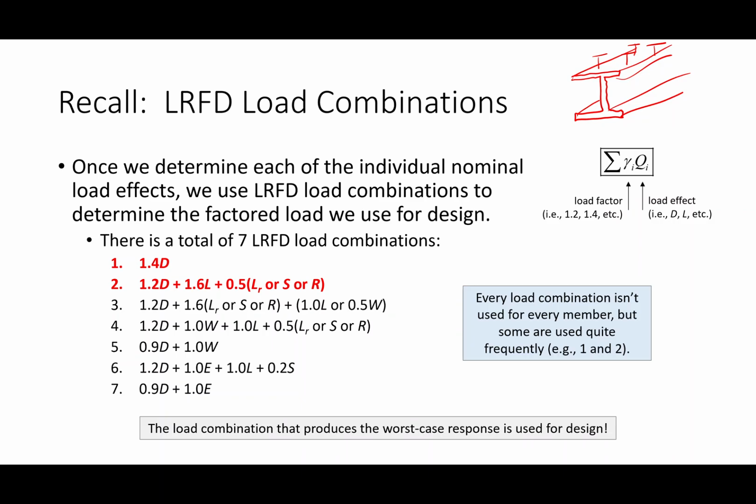Now, what is composite behavior? Here's what composite behavior is. So I have here my steel manual, and if I take these pages and I bend them, it's really easy to bend them. And the reason why it's easy to bend them is I'm not bending one beam. I'm bending like 500 beams that are all really, really tiny, okay? Now imagine I had a whole lot of time on my hands, and I took each one of these pages and I glued them together, okay? And then I tried to bend them. It'd be a lot harder to do that, wouldn't it, right? Because it wouldn't be 500 little beams, it'd be one really big beam, right? They'd all be behaving together. And when I say composite behavior, that's what I mean, okay?